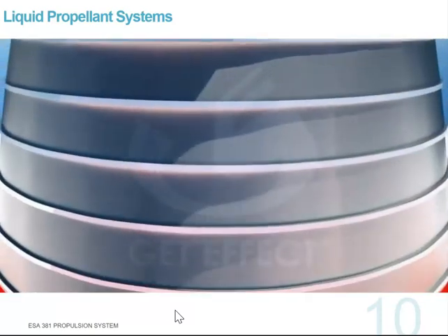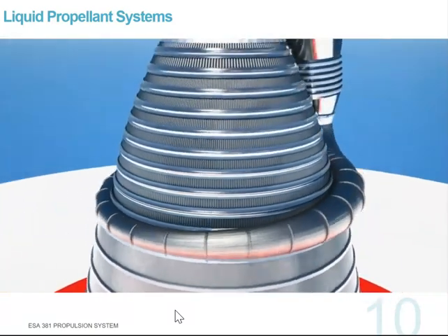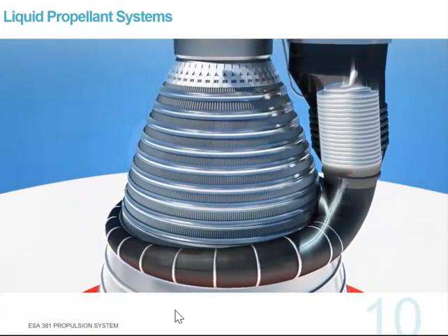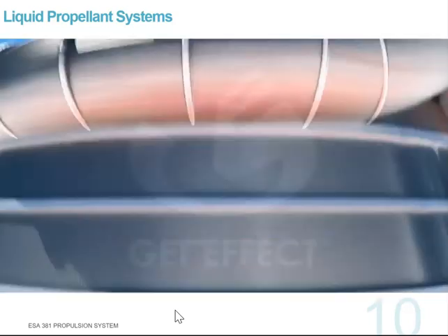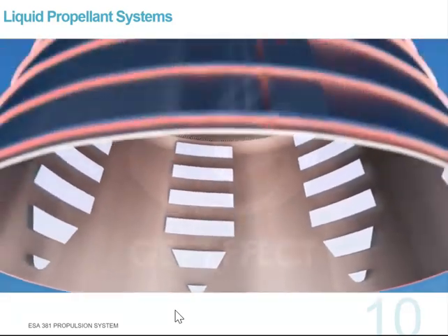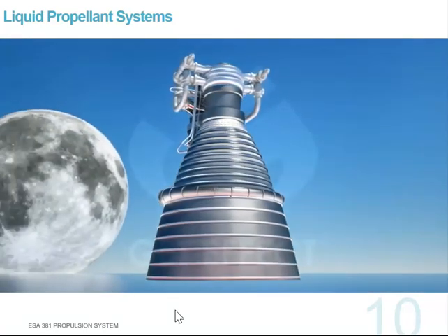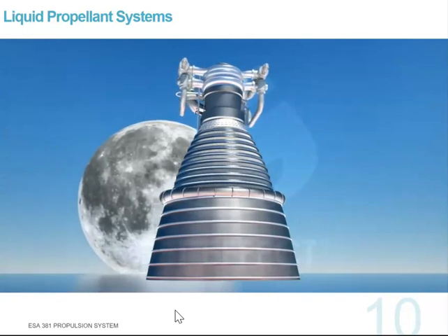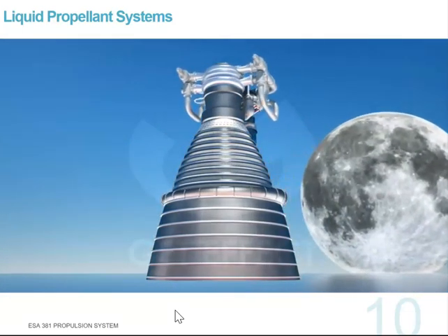The extension's wall was protected differently, by a barrier of cooler gases from the heat exchanger. These gases, at 660 degrees Celsius, were discharged alongside the upper side of the thrust chamber extension inner wall. The impressive F1 rocket engine remains, to date, the most powerful single-chamber liquid-fueled rocket engine ever built, and successfully operated.